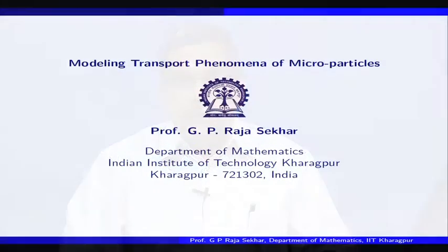Hello. In the last lecture, we discussed an introduction to flow through porous media. In particular, we discussed some basic models as governing equations. The first model that we discussed is the Darcy equation, which indicates that the volume flux is proportional to the pressure gradient. In the second, we discussed the Brinkman equation, where you have viscous terms. And then we discussed various possible interface conditions.